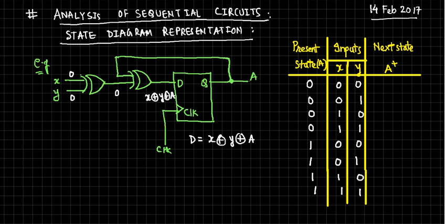So as soon as the next clock signal comes, as soon as the next positive edge comes, what would be the next state? That will simply be, just because it's a delay flip-flop, a D flip-flop, it will simply copy that data, right? So it will be 0. Is that okay?